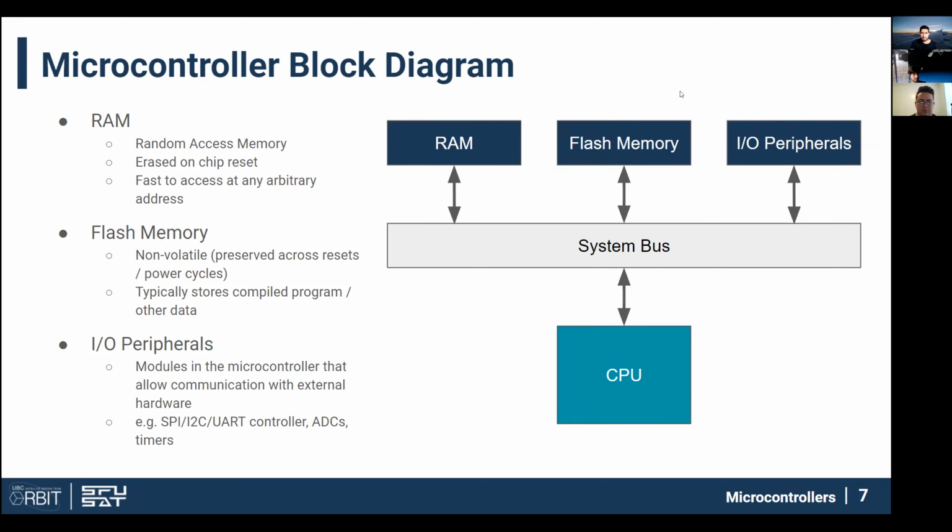Then there's flash memory, and that's non-volatile, so it's preserved across resets and power cycles. That typically is where you store your compiled code, so that's where your code actually lives. And you might keep data there that needs to be saved for future use. Then there's I/O peripherals.